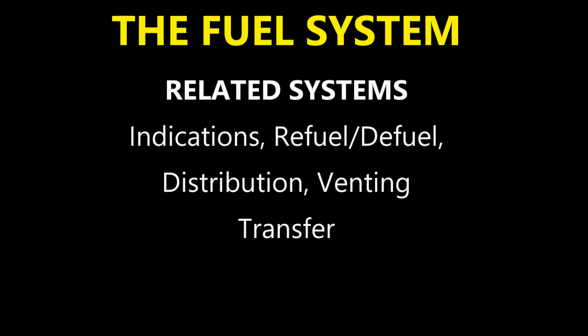Okay, with recirculation, you also have the check valve, and that's on the lower surface of the wing bottom skin in the engine pylon. With the check valve, you've got the connection between the recirculation pipe from the engine and the recirculation pipe in the wing. Okay.